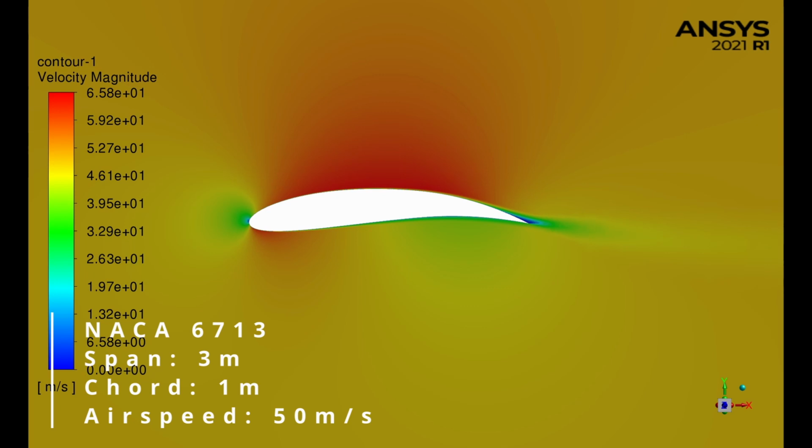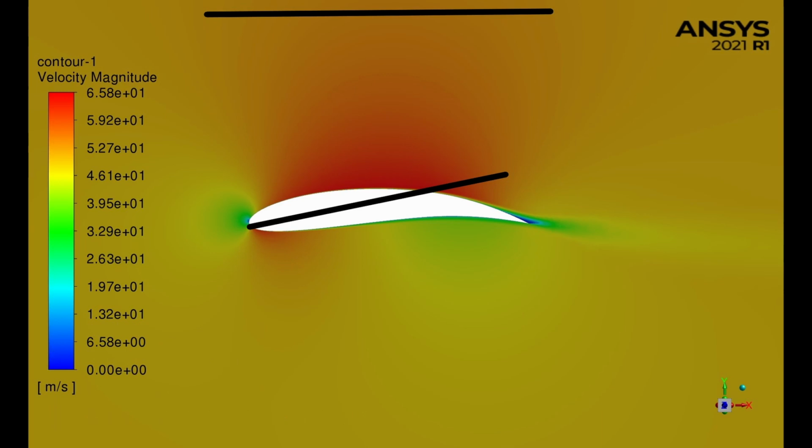What you can see here is a 2D slice in the center region of the airfoil, showing the velocity magnitude. It is fairly hard actually to describe the velocity and pressure distribution around an airfoil, and it's not entirely intuitive. I'll just give a super basic explanation here to not bore the people that already know about it. The way to look at the top side of the airfoil here is to look at it like you would a nozzle in a water hose. Of course, the airfoil is not completely round or sealed off, but the example still kind of works.